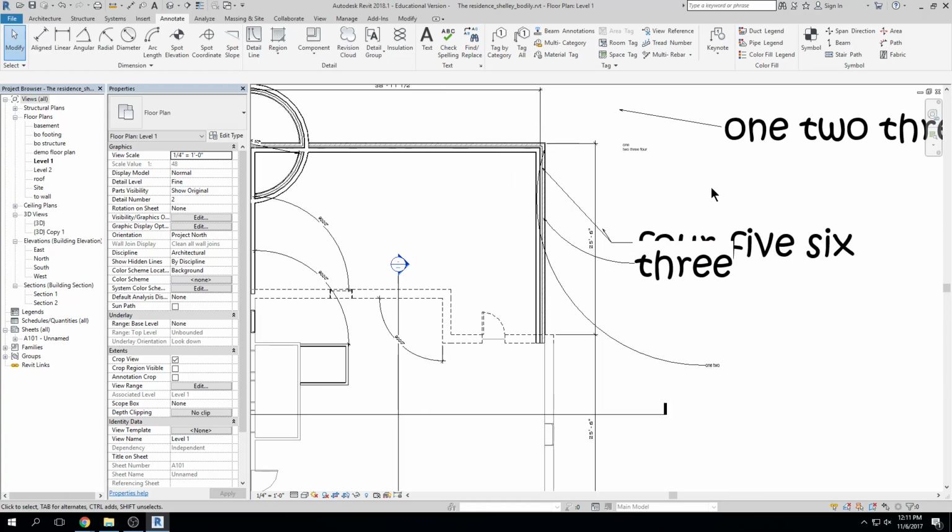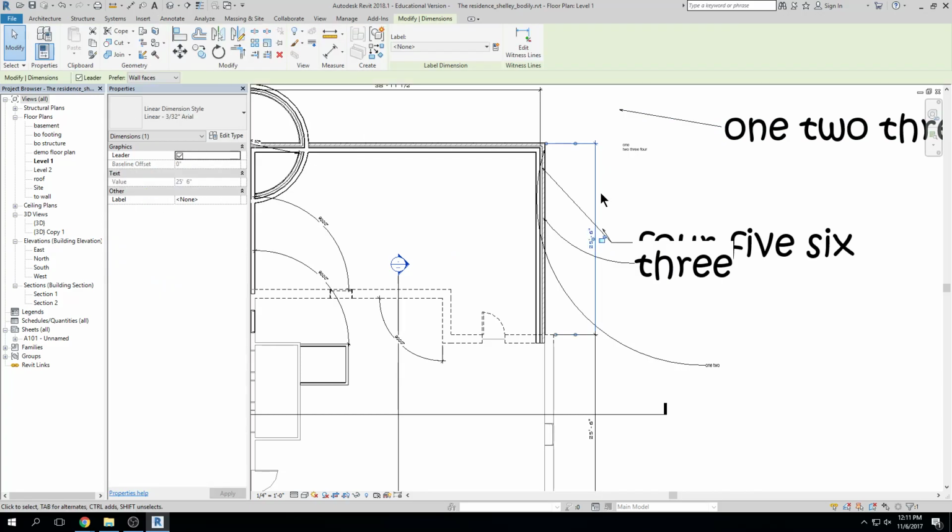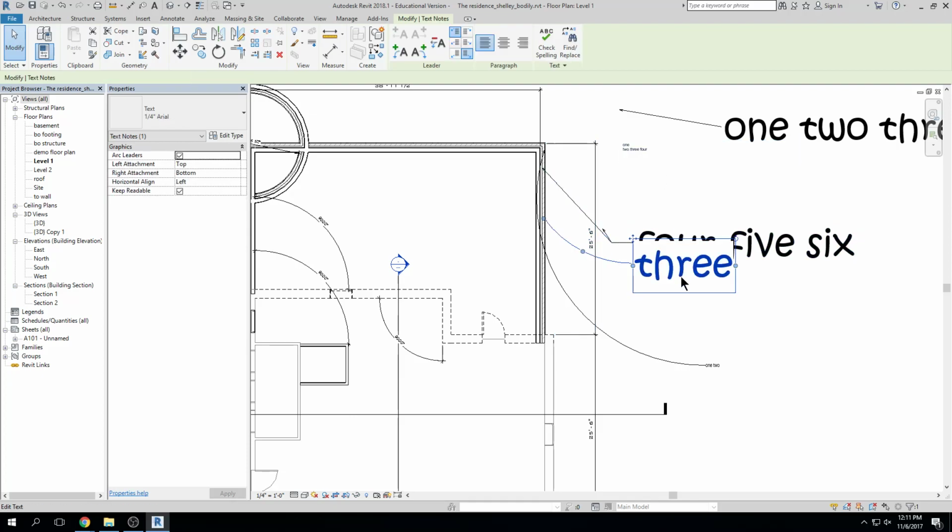You'll have a text style for your dimensions, a text style for your notes on your page, like your general notes, and then one for your leaders, which should be similar to your dimensions. Usually the reason you're going to change it is because maybe your office doesn't like Arial. They use City Blueprint or whatever. So you're going to set a couple up according to your office standard, essentially.